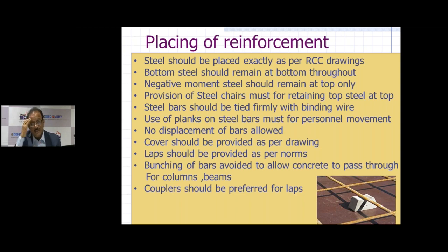And imagine, in a huge project there will be lakhs and lakhs of laps to be provided, and how much steel we are wasting. And if we provide the couplers, we will not only save the steel that is wasted in the laps, but also we are using couplers which allow us to freely place the concrete in the section without any segregation. So that is very important.